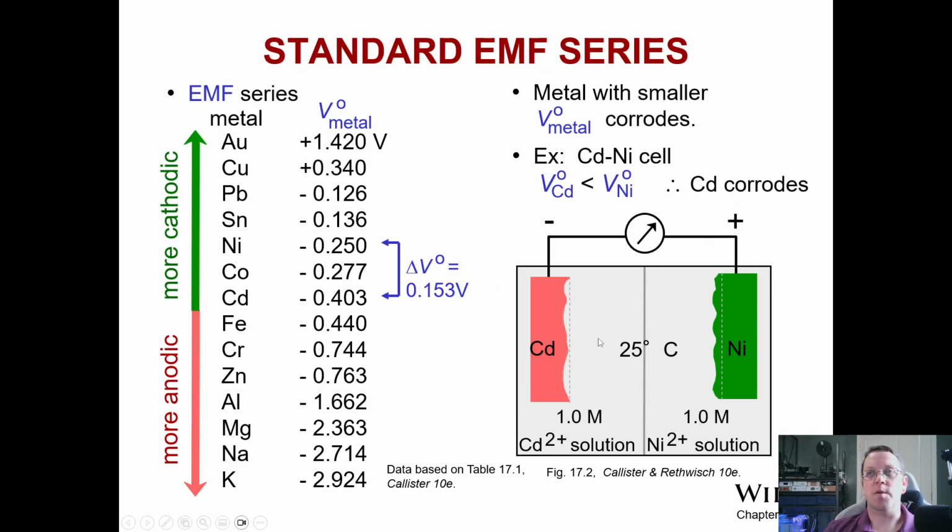The cadmium corrodes, and the nickel gets plated by the solution. So you see the erosion of the cadmium and the plating of the nickel from the solution. Once you deplete either side of this, if these reservoirs are unequal in volume, that current no longer flows, because once you have no more cadmium to degrade or no more nickel to plate out of solution, the battery is spent.